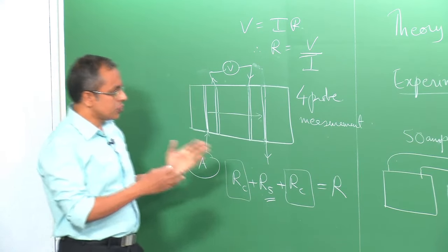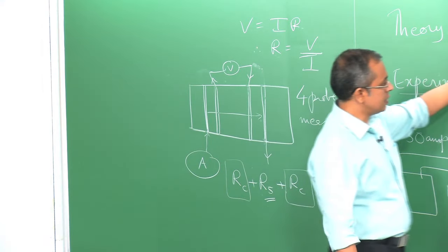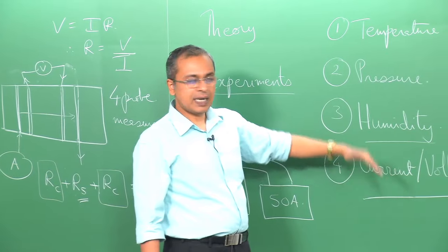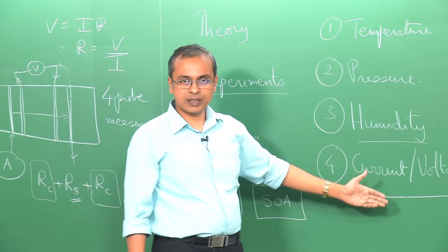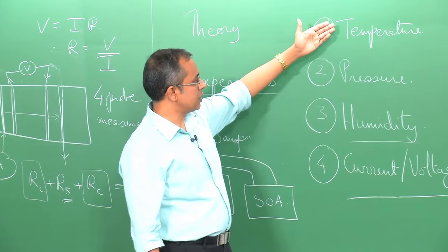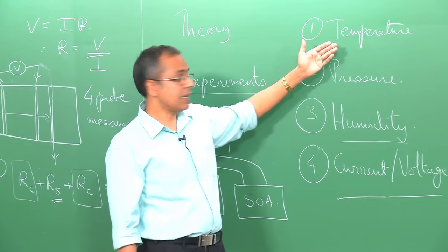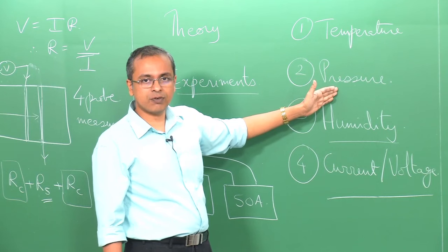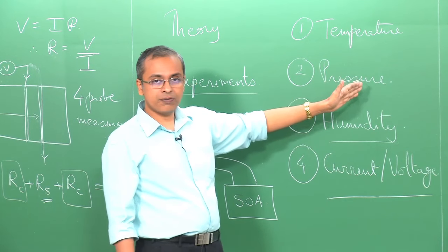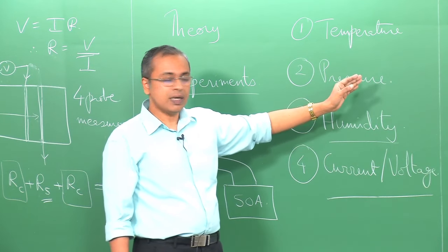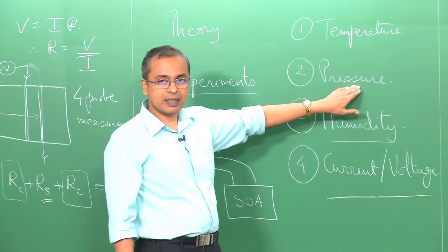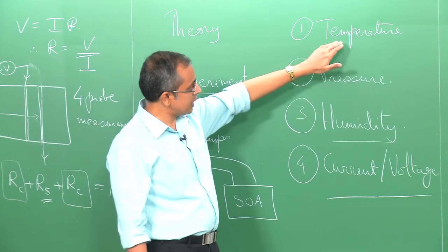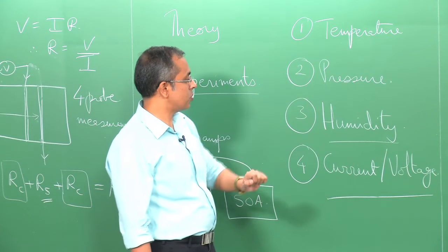So, to sum up, we have seen temperature, not a whole lot on pressure, but humidity and current and voltage, and I have just shown you that these are all common quantities that you measure. I just pointed out that there is so much room for error based on where you may put your sensor, similarly where you would put your sensor here for pressure, what kind of impurity or dirt for example covers the sensor, the location of the sensor or any other impurity that is on the temperature sensor also.